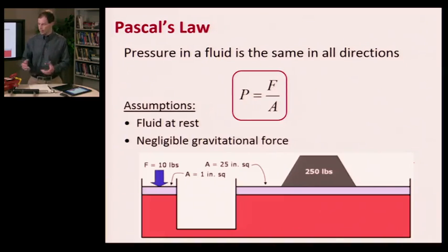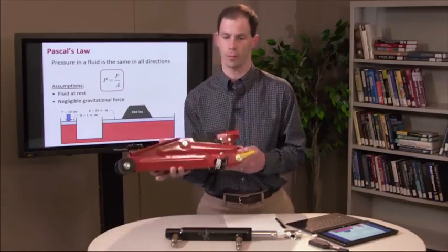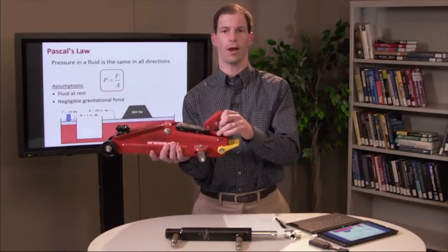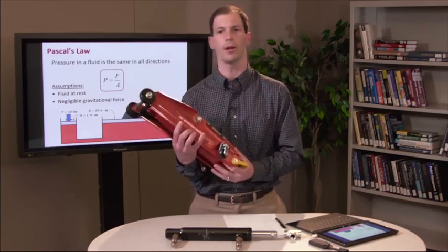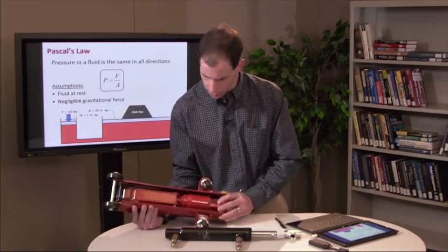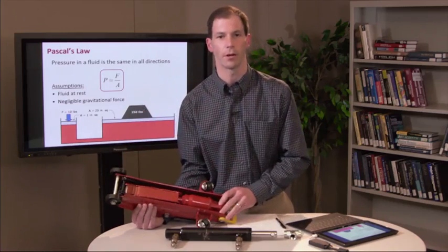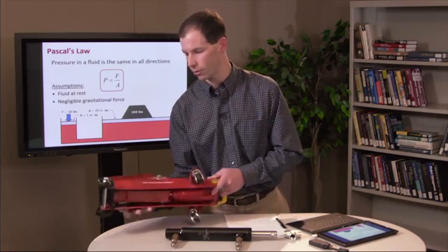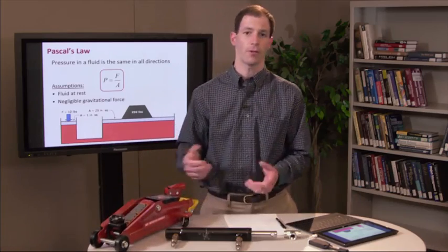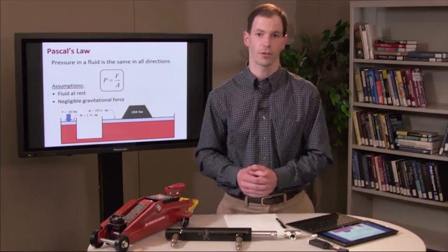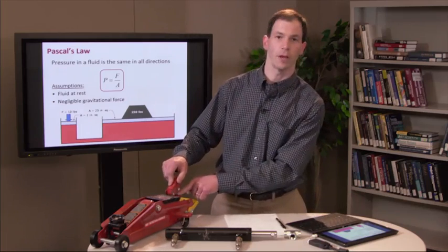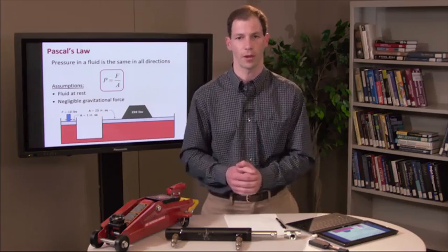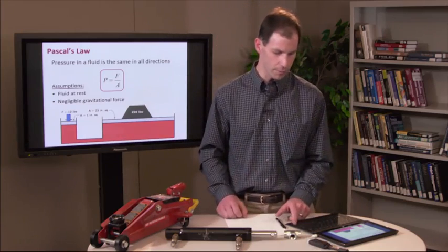So this is really the key to all fluid power systems, where we're creating a force amplifier or sometimes a flow amplifier. And if you look at this car jack right here, this is a prime example where I've got a small piston, which would be my input right here, and I can apply a meager amount of force to this, nowhere near what I need to lift a vehicle. But then you look underneath here, and I've got a very large diameter piston right here. The pressure is the same in the fluid, both in that small piston and the large piston, but I can amplify my force. And we're either amplifying force or we're using this to do precise position control, because you can imagine if I move some volume with this small diameter cylinder, I'm not going to get very much stroke with a larger diameter cylinder. So we can use this for precise positioning control and also force amplification.